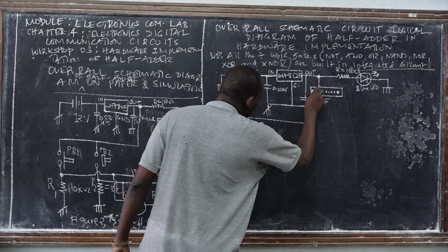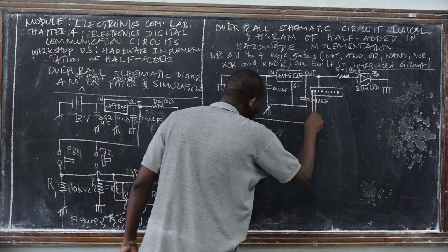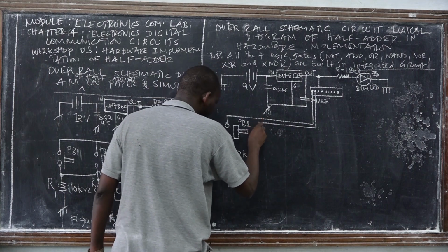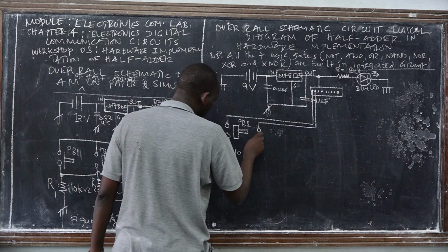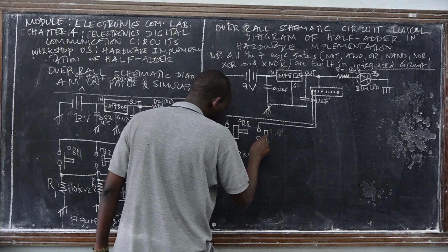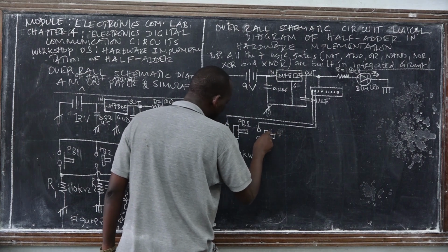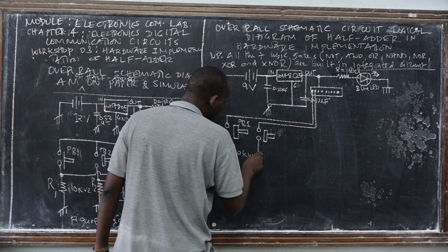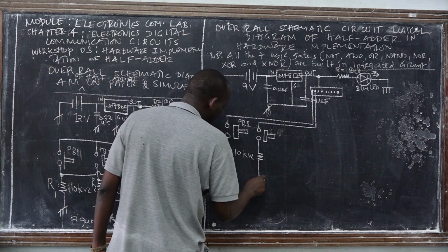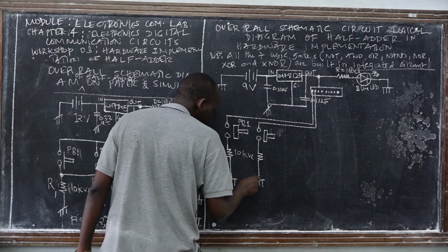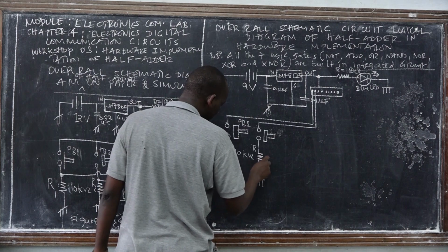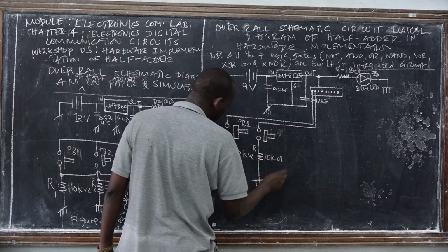Then we take another jumper or copper to draw power from the T block and connect it to the second pull down resistor network. In simulation you use something you call the logic toggle to simulate. In hardware we don't have a logic toggle. So this is a resistance of 10 kilo ohm.